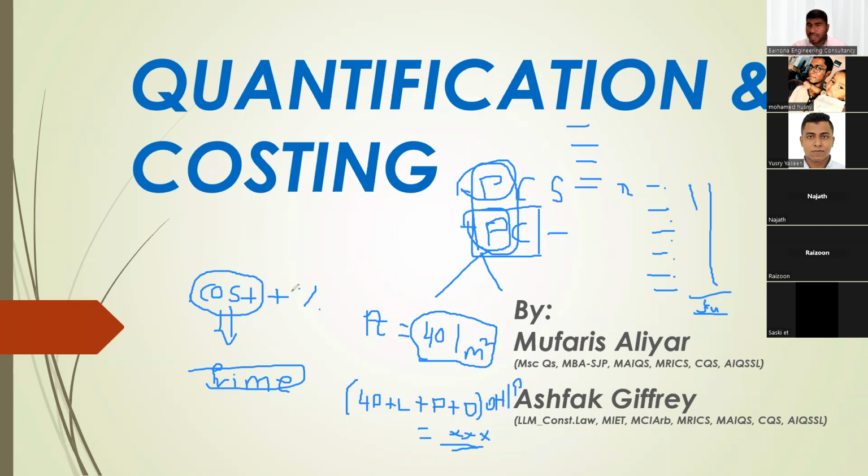Here, if you don't give a PC rate, I'm telling you that you have to give a specification and vendor list. If there is no specification and vendor list during the tender process, the PC rate comes here to limit the contractors from going here and there. So we advise the contractors, this is the material price. On top of it, the contractor may add labor, plant, material, whatever it is, and his overhead and profit. That we cannot decide. The overhead and profit of each contractor is something different.